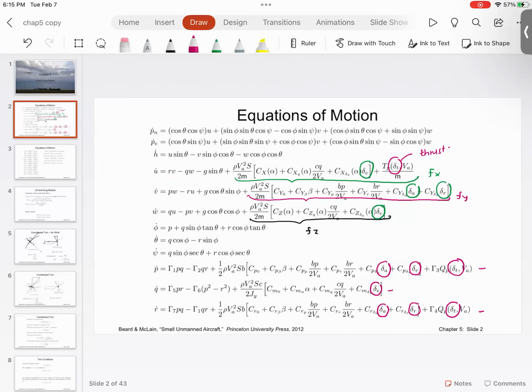What it means is there is a simplified representation of these equations that we can realistically solve. And if your flight regimen is non-complex, what do I mean by non-complex? For example, level flight. If the aircraft is in a level flight, or in a simple coordinated turn, or if the aircraft is sort of loitering, these are very simple maneuvers, because if you take a very small snapshot, all the states will behave linearly.